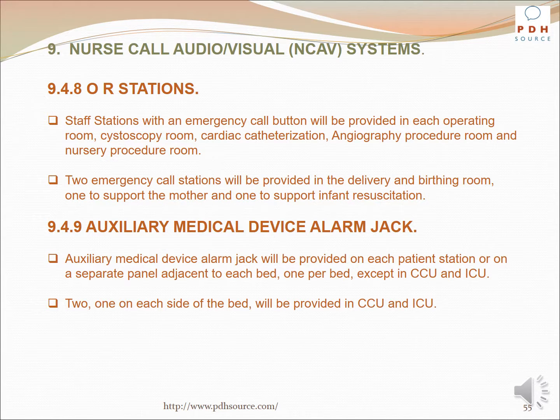Operating room stations, staff stations with an emergency call button will be provided in each operating room, cystoscopy room, cardiac catheterization, angiography procedure room, and nursery procedure room. Two emergency call stations will be provided in the delivery and birthing room, one to support the mother and one to support infant resuscitation.